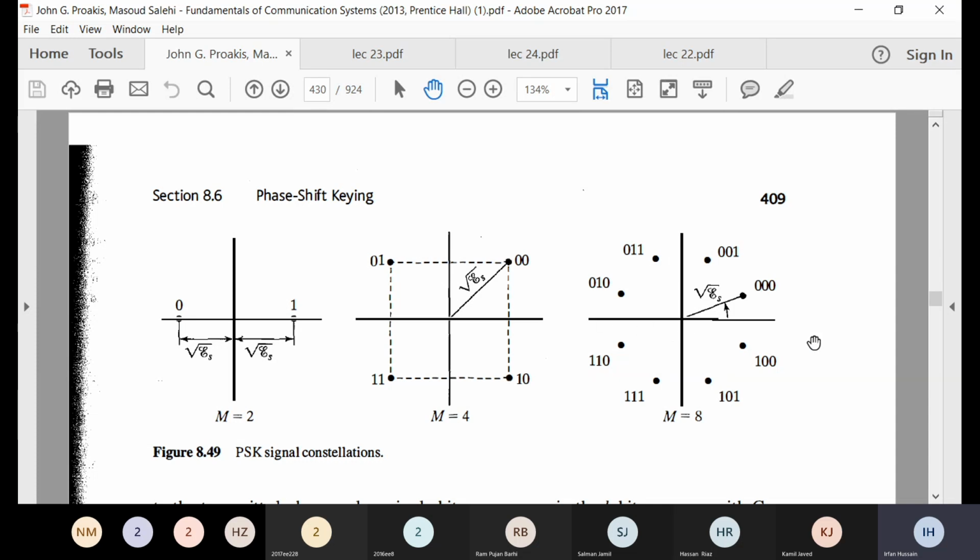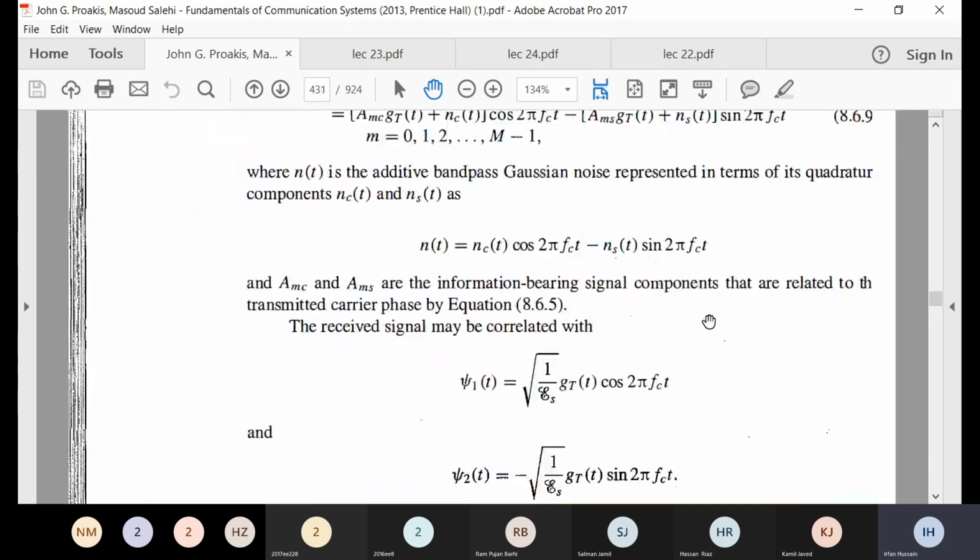Now these could be any orthonormal basis. It's not necessary that you have cos and sine. Yes, cos and sine are used industrially. We have just seen, when we were studying amplitude modulation in chapter 3, that cosine and sine are the basic norms. You can carry double the signals because they are orthogonal, and then you can separate them. So here, why not use them? You have cosine as the orthonormal basis for the x-axis, and sine for the y-axis, so they are orthogonal. As we saw those pulses of binary, we can also use cosines and sines, and you can have these schemes.